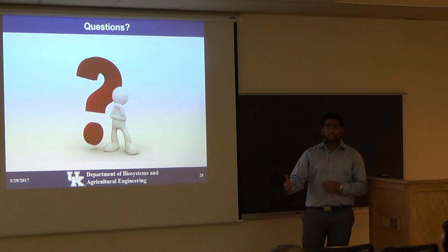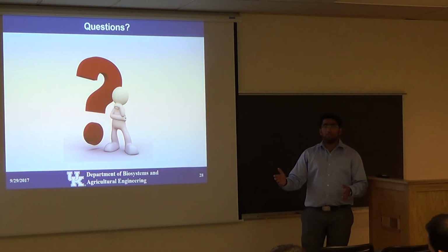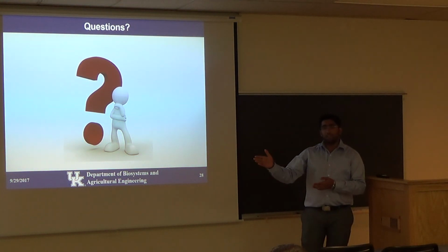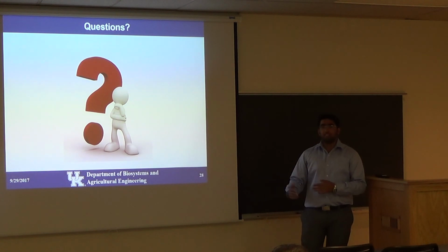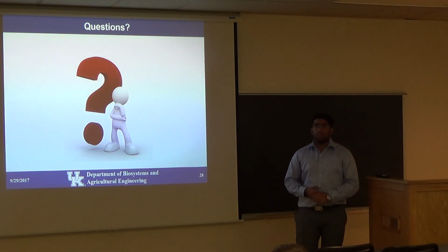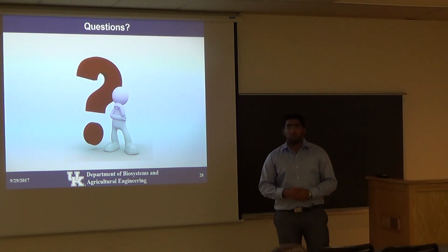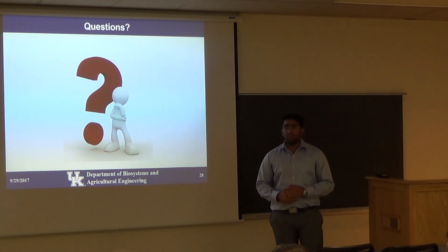So we will remove the data which is more than 1 meter from the LiDAR. If it has a y coordinate which is more than 1 meter, it will be removed. We will remove all those points from the data, checking the x, y or z coordinate. So basically screening out everything that isn't in the fixture. Exactly.